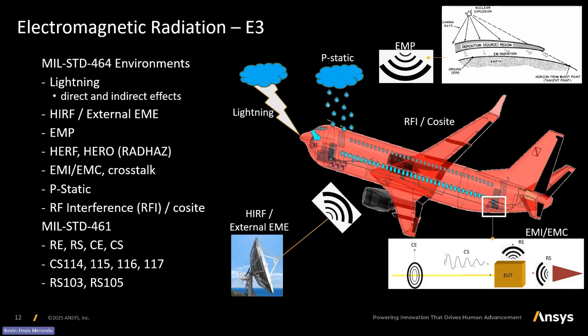And so here for electromagnetic environment effects, you can see things like lightning attachment, which will have current flow through a structure, but also indirect lightning effects. We have electromagnetic pulses that can be generated from natural causes or not, and that will interact with the aircraft. There's various statics, and there's also antennas that will emit radiation in various profiles with various frequency spectrums that we have to be able to handle and shield ourselves from in some cases as well.